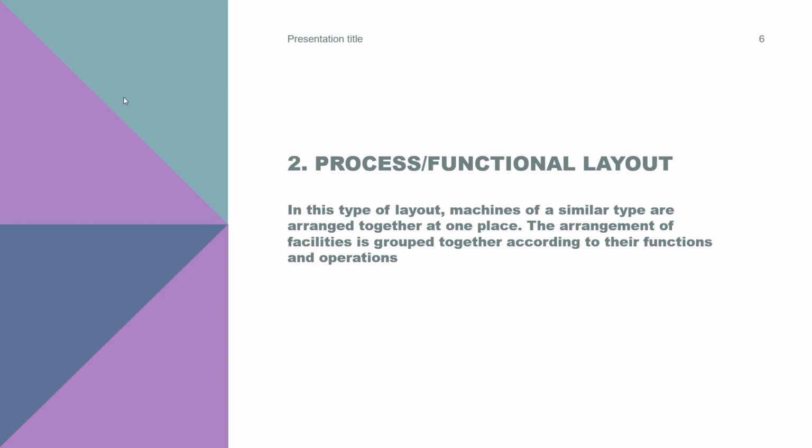Now we can study the next disadvantages of process layout. Material handling costs are high due to backtracking. More skilled labor is required, resulting in high cost. Next, time gap or lag in production is higher. Work in progress inventory is high, needing greater storage power. And the disadvantage is more frequent inspection is needed, which results in costly supervision.